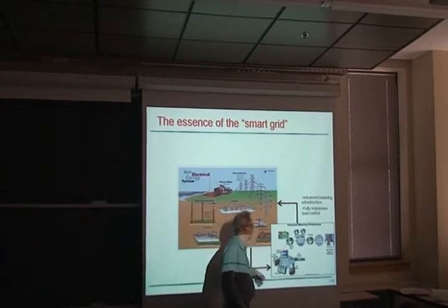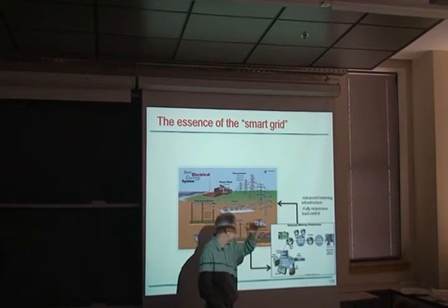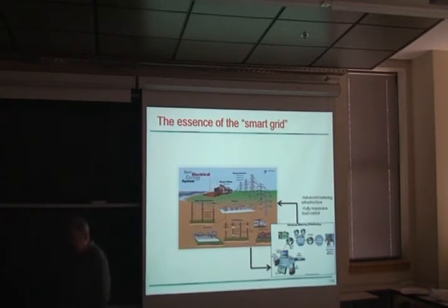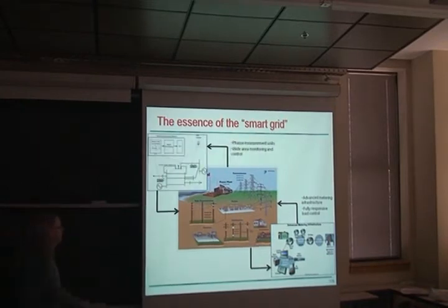Taking measurements through the advanced metering infrastructure that's been rolled out, applying control to alter the load characteristics. That's at one end, and at the other end, at the higher voltage transmission end, it tends to take on the form of what's called wide area control, where you're taking measurements from across a large, geographically large area, time synchronizing using GPS, and then building a control algorithm that takes into account these wider measurements to implement various changes on the grid in real time.